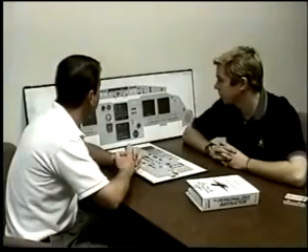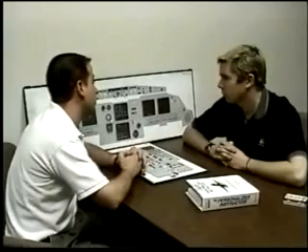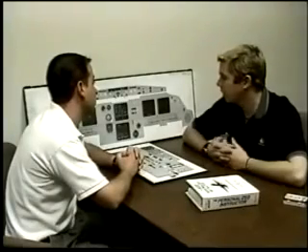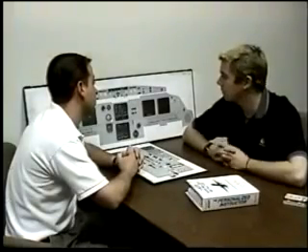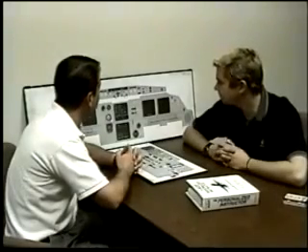What about the scenario of losing both channels of the BSCU, but we still have green hydraulic system? If I've got green hydraulics, but I lose the BSCUs, I still lose my normal brakes, and I lose anti-skid capability. Okay.